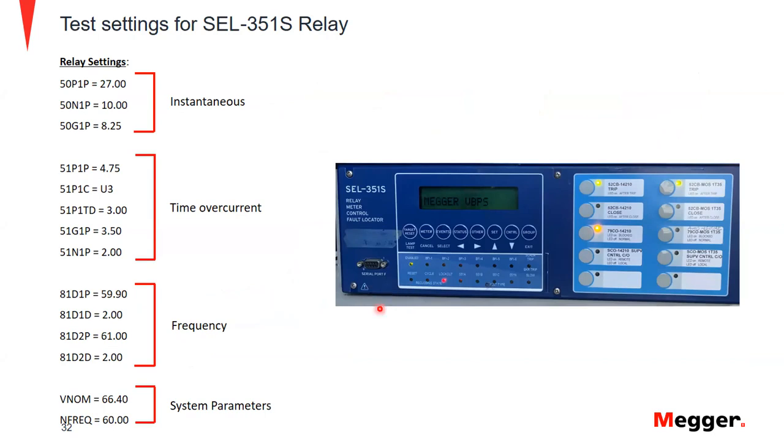So we're gonna jump on this 351S, kind of give you guys a little look at my settings here. We're not gonna have a huge amount of time to go through each individual test, but we are gonna try to at least hit the pickups and at least hit the time current curve for the phase. And then we also want to hit some of the tests for the frequency when we do a frequency pickup along with a time delay.